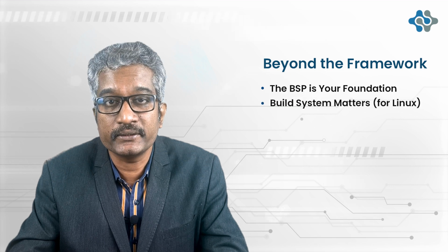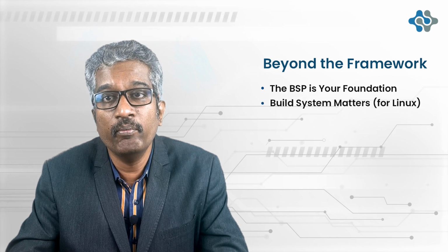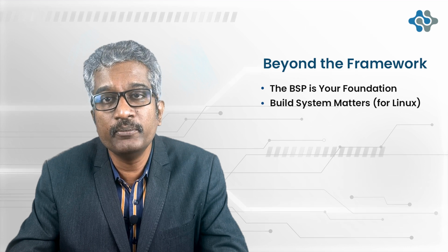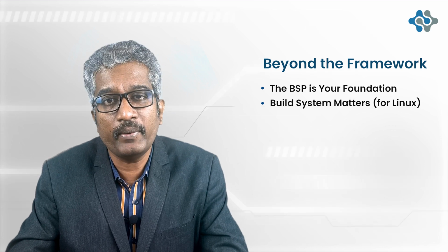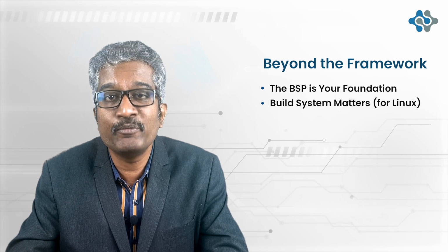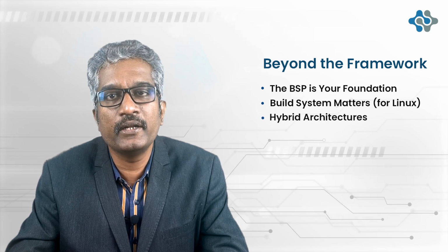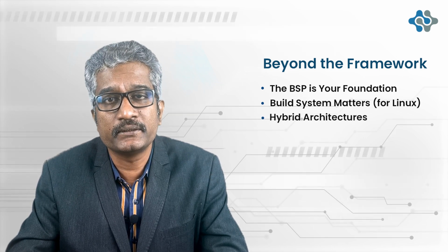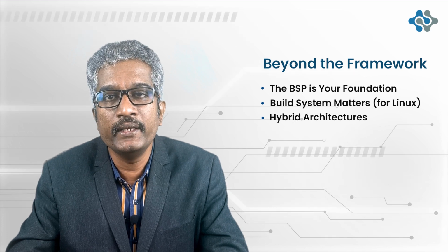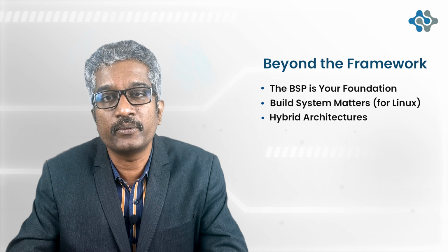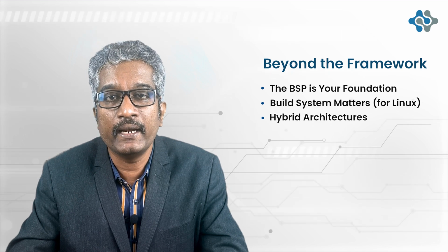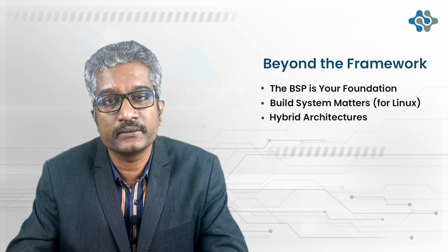Build system matters. Choosing between Yocto, Buildroot, or a simpler approach within Linux has huge implications for customization, complexity, and long-term maintenance. This is almost a sub-framework decision itself. Hybrid architectures. For complex systems needing both hard real-time and a rich OS GUI, consider a multiprocessor approach or a hypervisor to run an RTOS on one core and Linux or Android on others.